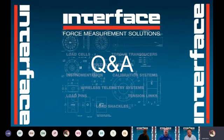You would need an amplifier typically between it and the Arduino. And most Arduinos have fairly low resolution on their analog to digital converter. So you may want something that improves that resolution, including an Arduino-based add-on A to D converter. But we have a lot of customers who are doing that these days.